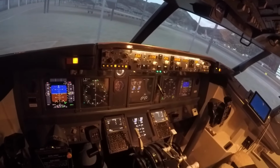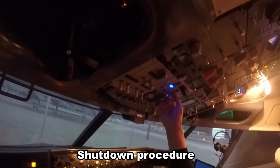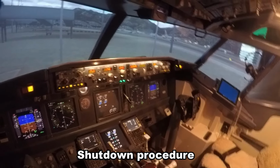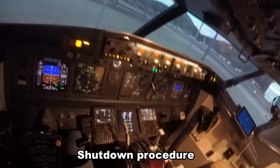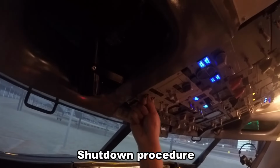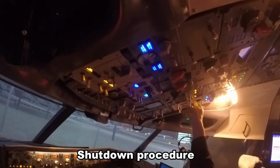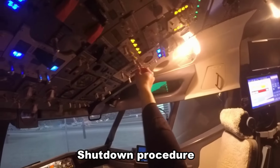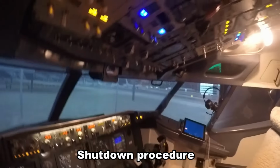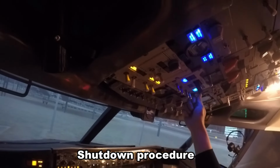So right at the gate, we'll just apply the parking brake. Alright, so we'll turn the APU on, and then we'll turn off the engines. So that's engine start levers to cut off. Alright, so fuel pumps going off except for the forward left one. Hydraulic panels set, isolations open, APU bleeds are open. The transponder off, the anti-collision light is off, fasten seatbelt signs off.